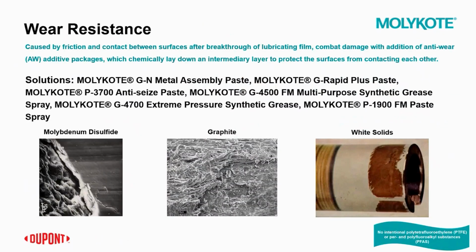So next we could look at wear resistance and additive packages specifically for wear resistance. Wear resistance additives and lubricants are essential for enhancing the performance and durability of lubricating oils and greases. These additives help reduce friction and wear of moving surfaces, improving the longevity of machinery and equipment. Additives that help achieve this effect include molybdenum disulfide, which is a solid lubricant that can be used as an additive in oils and greases. It provides excellent load-bearing capabilities and reduces friction and wear, especially in extreme pressure applications.